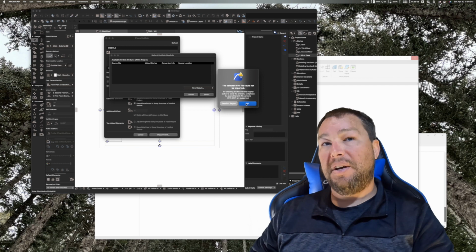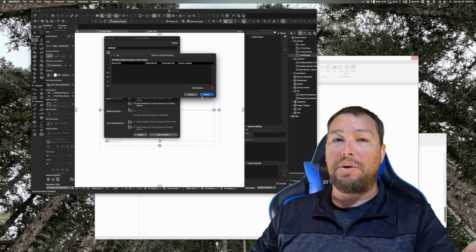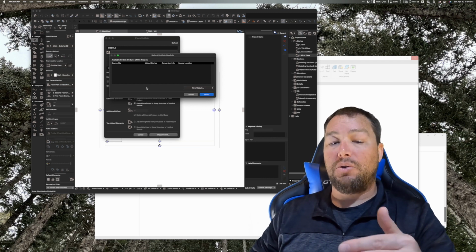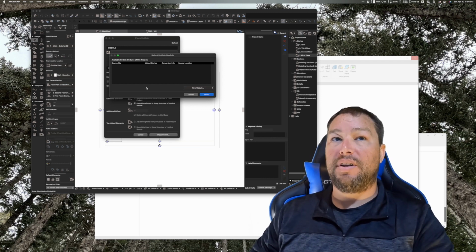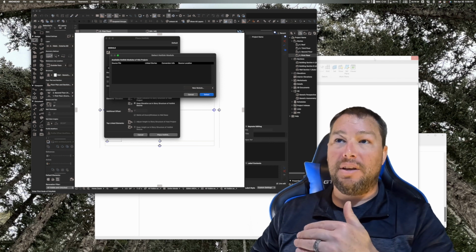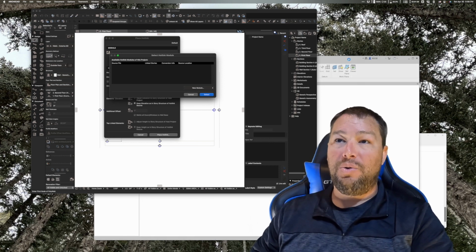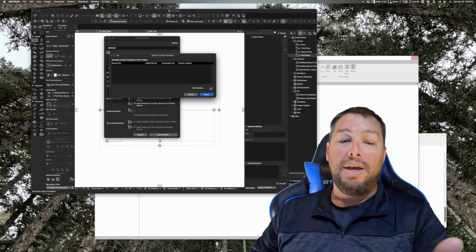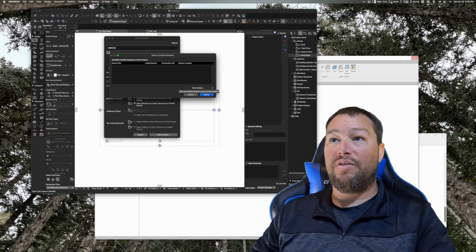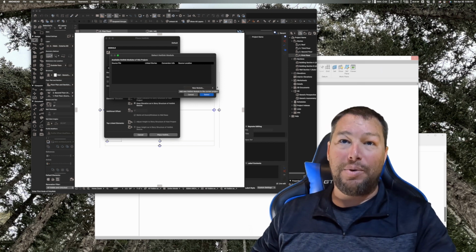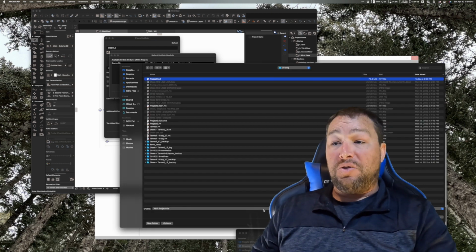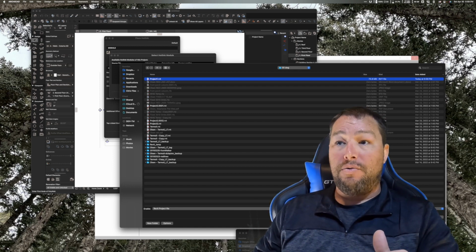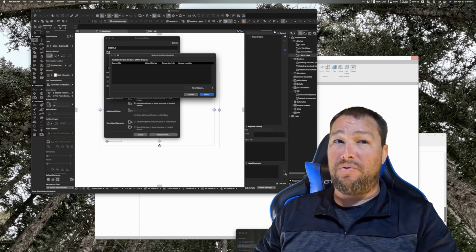okay. So as you can see, there's one problem. We need a file that is a 2015 to a 2021 version of Revit. I'm actually running Revit 2022, and the file that I just tried to open up is actually prior to Revit 2015, so I cannot open up that file. So let's try that again, this time with a Revit file, hopefully from Revit version 2015.